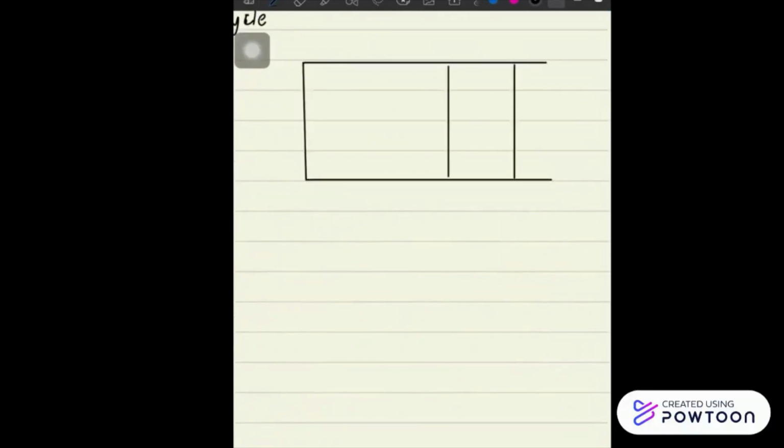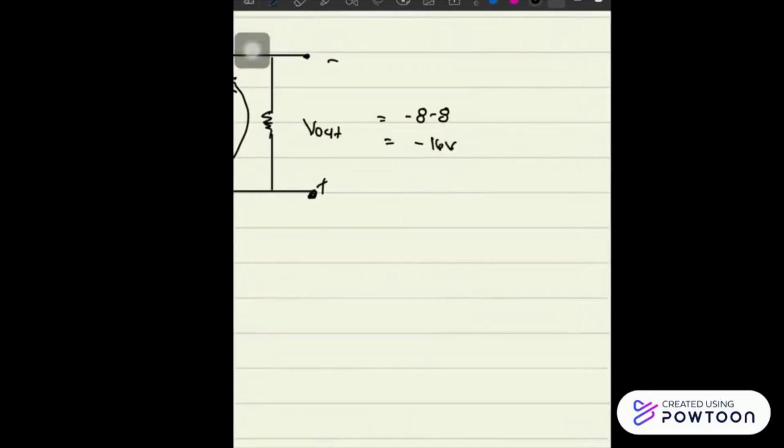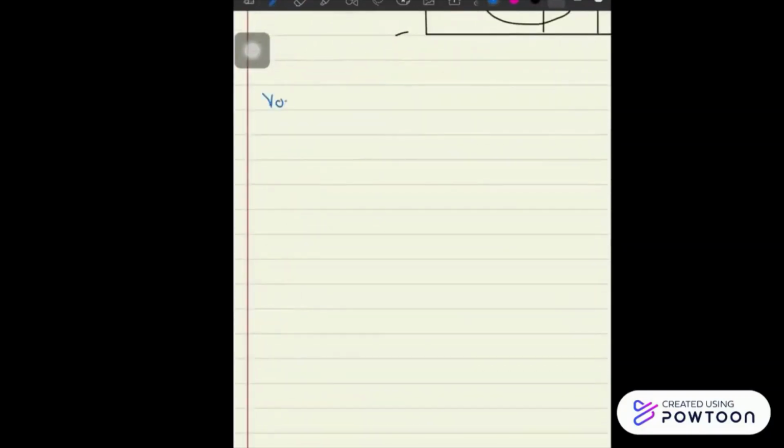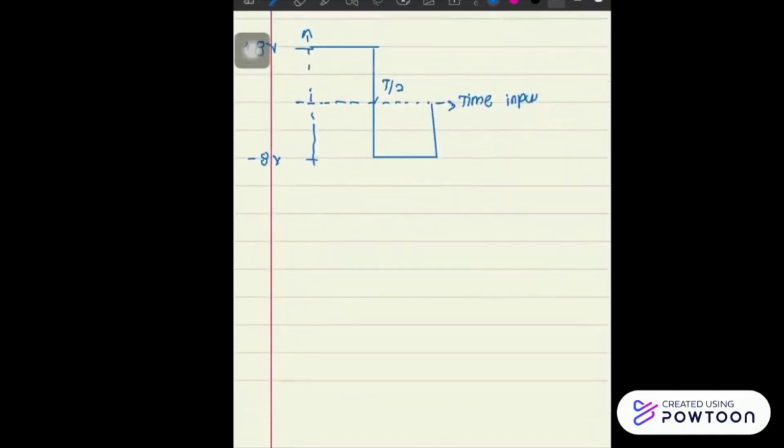When the input switches to the negative state, the network will appear as shown with the open circuit equivalent for the diode determined by the applied signal and the stored voltage across the capacitor. Current flows through the diode from the cathode to anode. Now that the resistor is back in the network, the time constant determined by the RC product is sufficiently large to establish a discharge period much greater than the period T/2, and it can be assumed on an approximate basis that the capacitor holds on to all its charge and therefore voltage during this period.